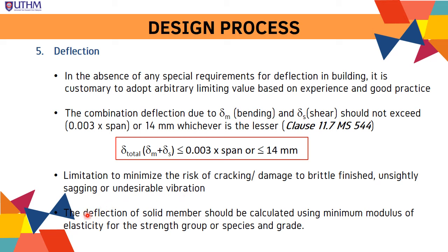For solid timber beams, the deflection should be calculated using the minimum modulus of elasticity for the strength group or species and grade.